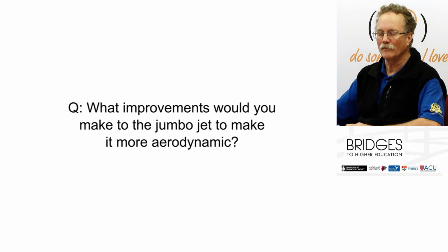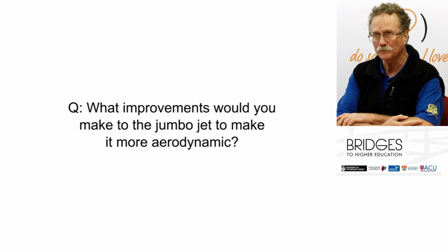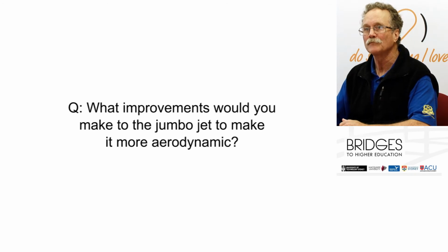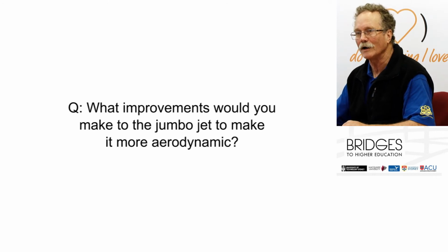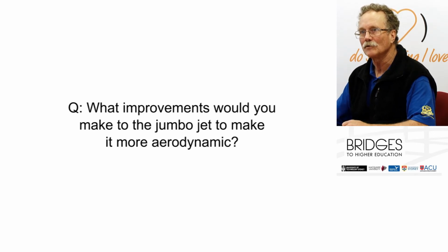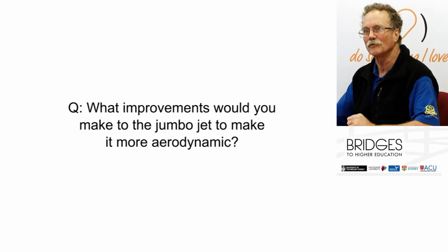Very difficult question, very hard question. Jumbo jet development started in 1969 and has been improving step by step all the way. So aerodynamic improvement is at its peak. The big improvement areas at the moment are in terms of reducing weight. So you've heard of the new Dreamliner, where we're now replacing aluminium and steel components with composites, which are same strength but much lighter. And if the weight is lighter for the same size aircraft, the lift can be less, therefore that lift-induced drag component is less, therefore it's more efficient.